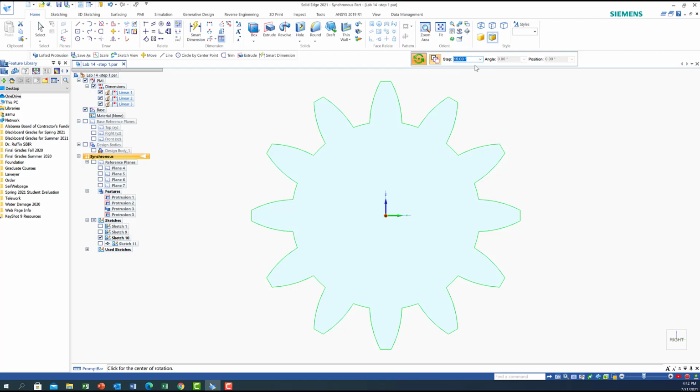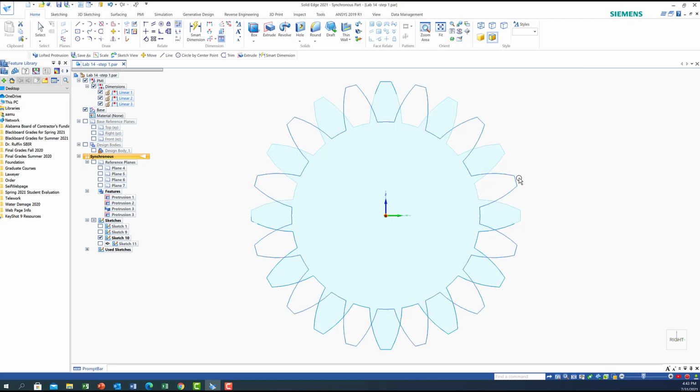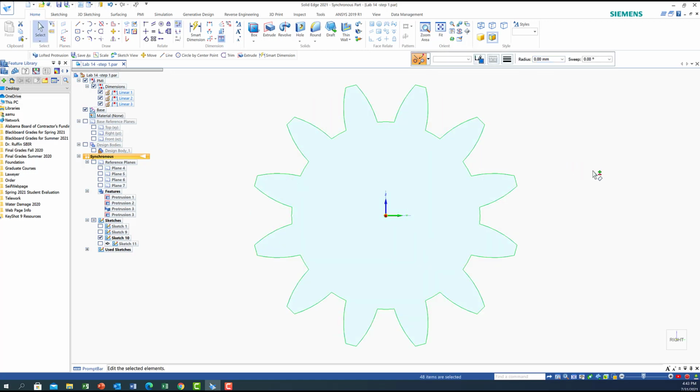Enter. And then, don't forget, we're going to press the control key and keep pressing it. I'm going to click at the center point, and then create a line to the middle here. Then I'm going to go up one step. Now remove your finger from the control key and click. This way I rotated it 15 degrees without doubling the sketch. Now let's save whatever we have. So we're done with this one.